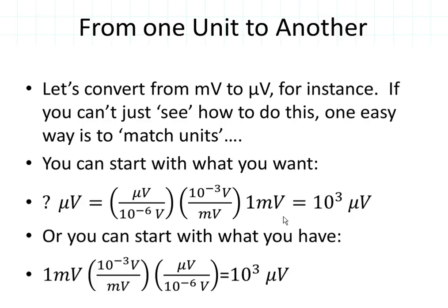Well, what we need to do is match units from this microvolt which we want to this millivolt that we have. So microvolt is 10 to the minus 6 volt. Are we there yet? Nope, we haven't gotten our millivolt taken care of. Let's say now we want to get rid of the volts and we want millivolts instead. So we're going to say 10 to the minus 3rd volt per millivolt. 1 millivolt is 10 to the minus 3rd volt.